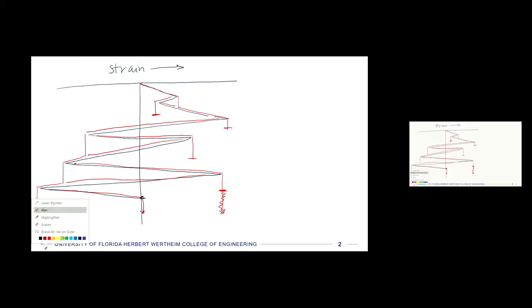Let me go with green here. We'll start at the very top. Our first rainflow counting went from the 0 position here out to where it ended. So we're going to count that as a half cycle, because we weren't coming from somewhere, it's not a full cycle. It's just a half cycle there. So that's our first count, 1/2 cycle. I'll just draw it on the top here in green, and I'll say half.